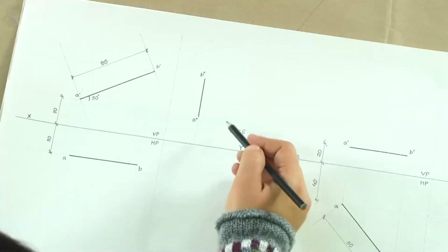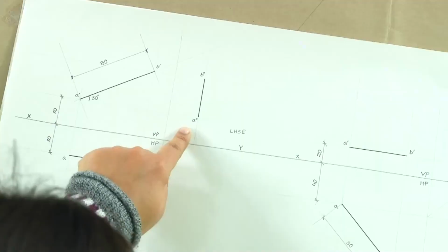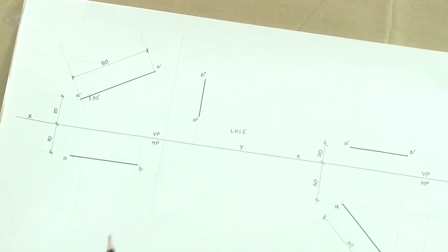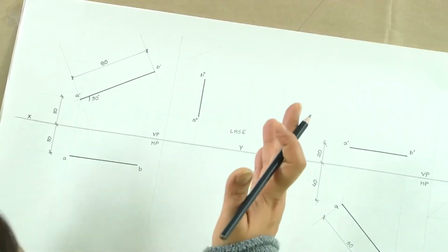Another thing that you have to keep in mind is the font size. So, the labeling of the sheet has to be appropriate size. If the font size is too big, then that will dominate. If the font size is too small, then it will not be readable. So, we have to have a balance between what size of font will be used. It has to be just proportionate to make your drawing look good, and then the drawing has to be distinct.